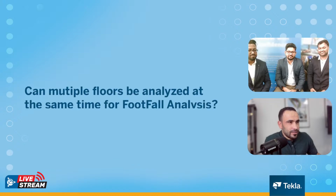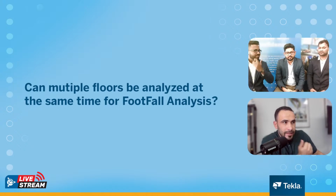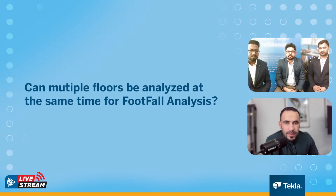Can multiple floors be analyzed at the same time for footfall analysis? Yeah, I believe with the 2023 release, yes, we will be able to analyze multiple floors simultaneously. So far you were able to analyze a single node or a particular line at once. But with the new upgrade, we'll be able to do multiple floor analysis, provided you provide all the restraints required as a prerequisite. You'll have to fulfill that, and then you'll be able to analyze it completely, simultaneously.